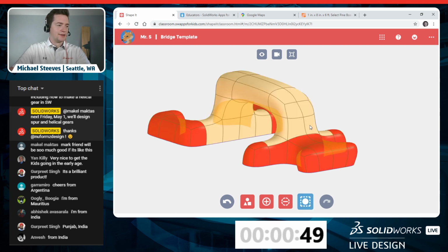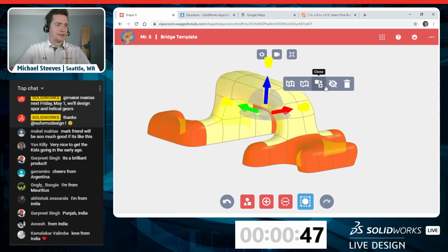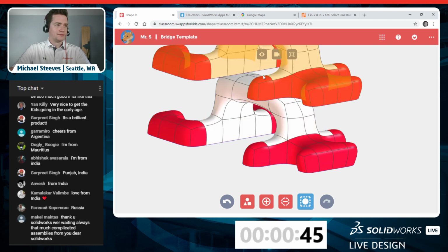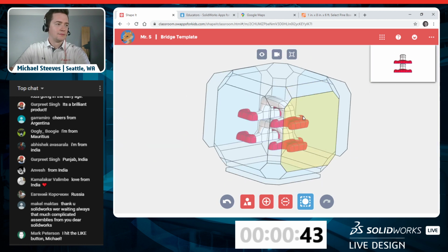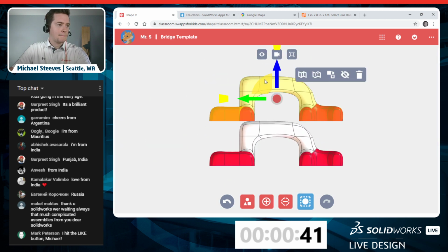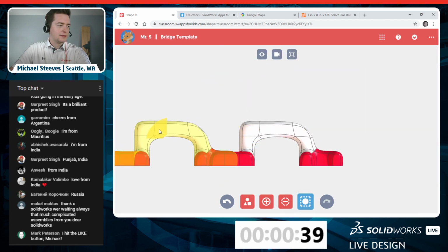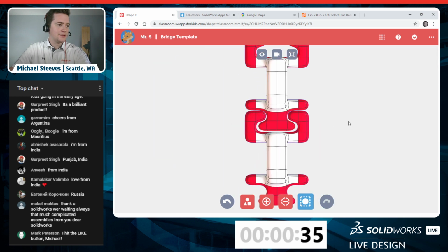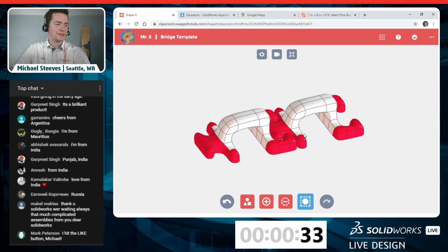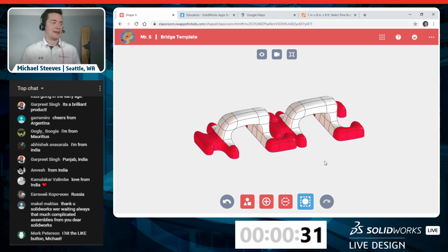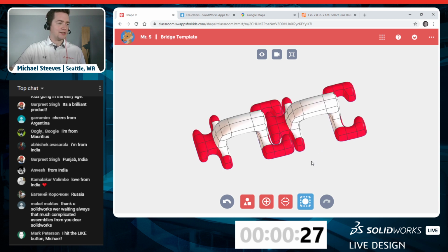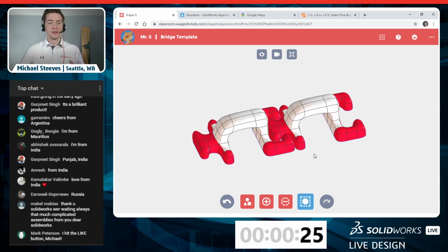And to connect those, I can duplicate a body, clone it, and let's eyeball it here. If we go to the top view now, yeah, it fits nicely together like a puzzle piece. So that's just a little simple exercise of using bridges and talking about design constraints: things that you can change, and things that you don't want to change, to build something that connects with something that other people have designed.